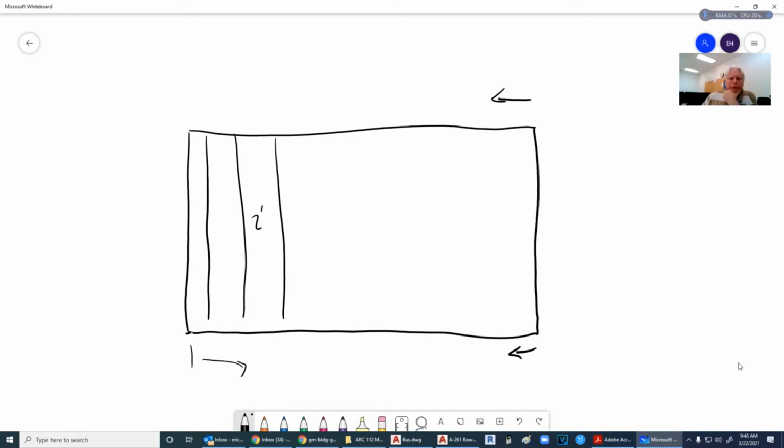Were they 2x8s or 10s, or what were they? I don't remember. These were the floor joists, and they laid them off from left to right. But when they went up to do the studs, they laid them off from right to left, which means the studs did not line up completely on top of the floor joists.